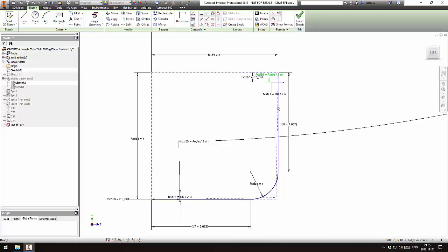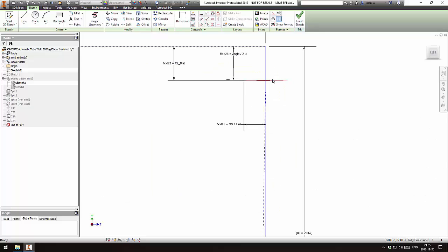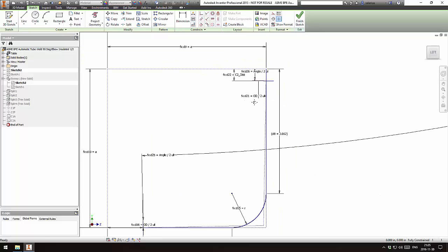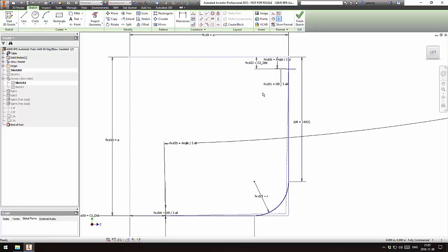And I've created these construction lines here, which will serve as my connection axis. And right here, where the split line is, because I'm using a split to trim the sweep, and I have another point there, those are my connection points. Yeah, so if you ever need to do something similar, keep in mind all you have to do is create directional lines which will serve as your axis and some points to where the connection will be.